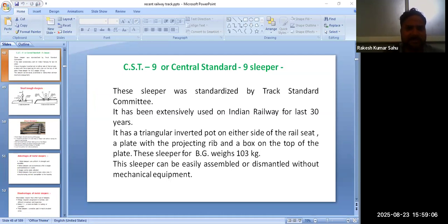Here are some main features of this concrete sleeper. This is a very basic sleeper. Normal PSC sleeper, its length is 2.75 meters, weight 260 kg, and service life is 50 to 60 years. These PSC sleepers are manufactured according to RDSO IRS P39 code and IRS P45 for turnout. New design has also been tailored by RDSO for DFC for M60 grade of concrete.